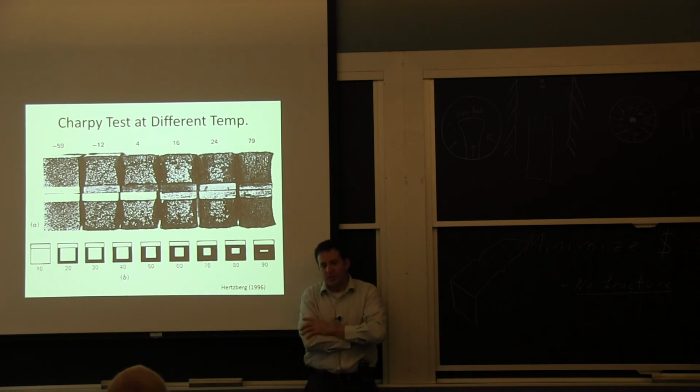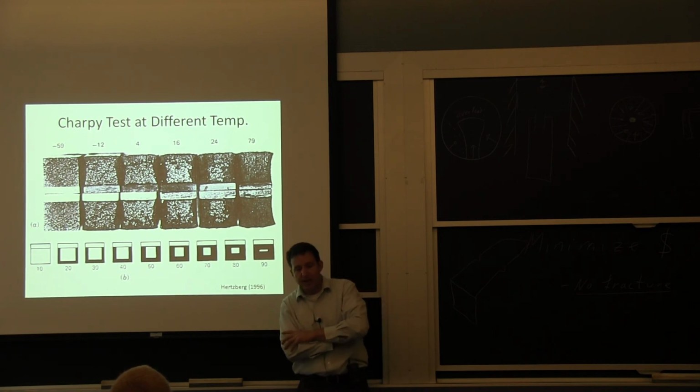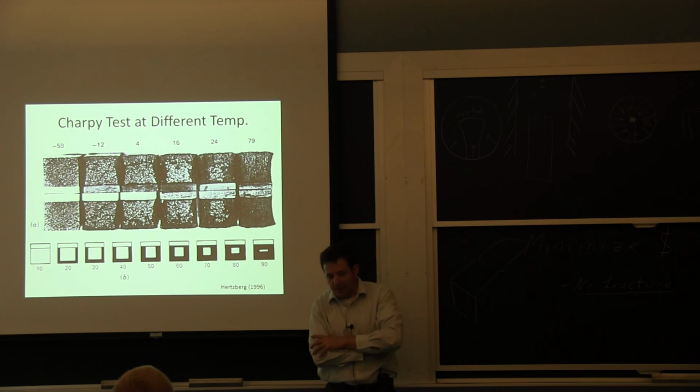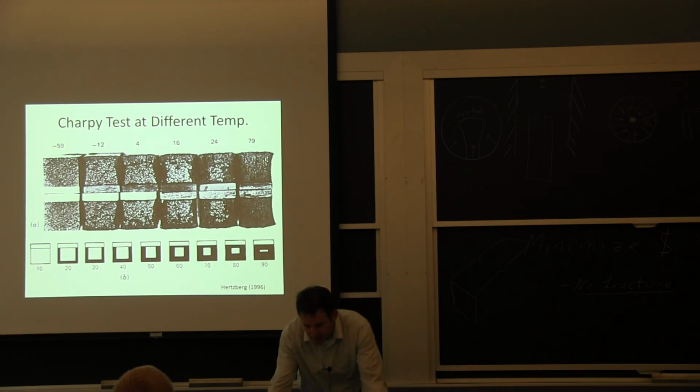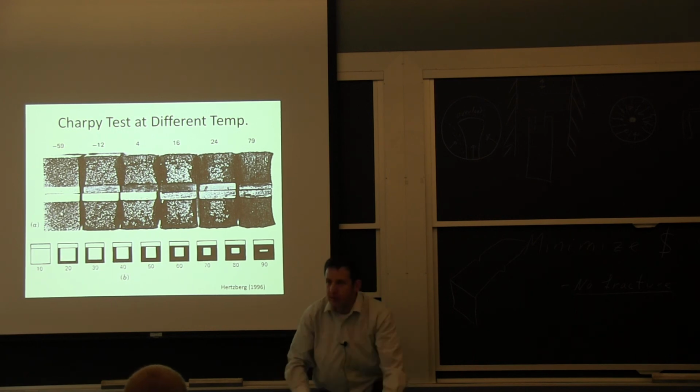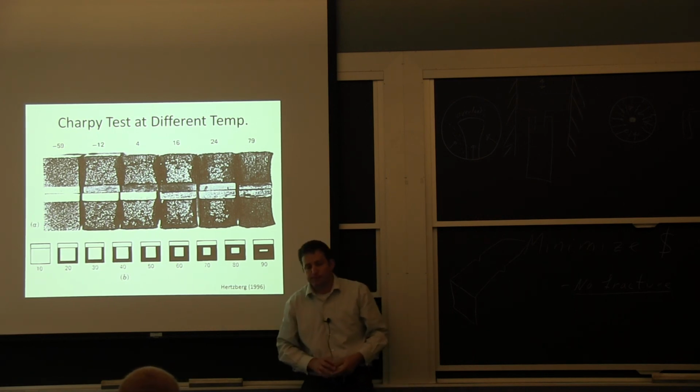What we do with these Charpy tests of steel is we end up making an evaluation as to whether it's a ductile tear fracture. So in this case here, they say it's 90% ductile. There's still a little area in the middle that is more of a brittle separation behavior. And as you reduce the temperature, you're going towards just a brittle behavior.